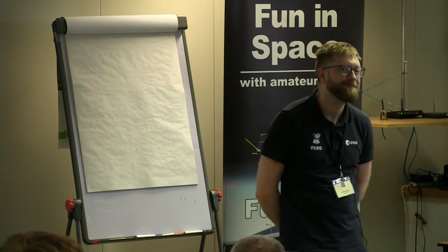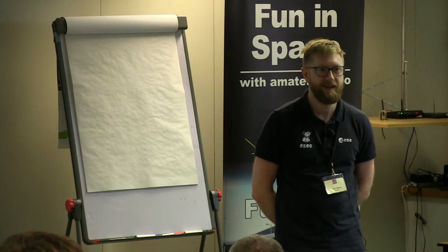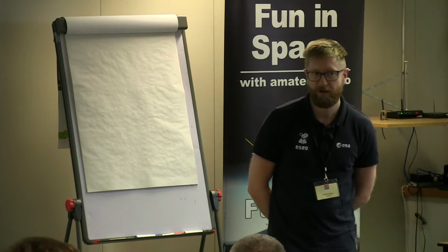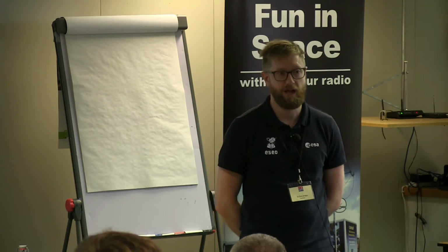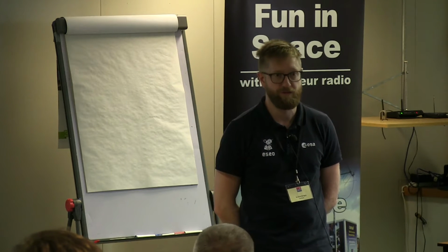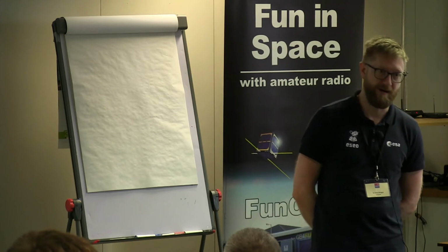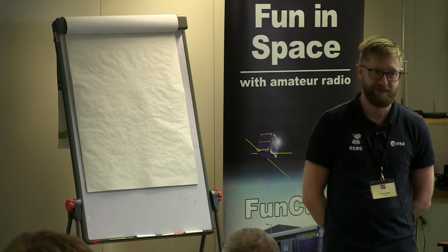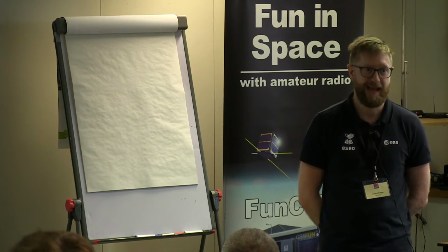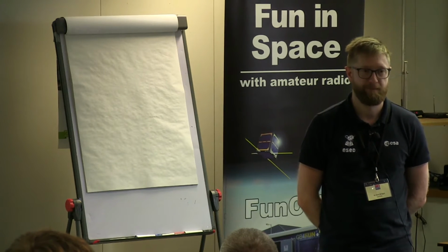A further question. SD cards. SD cards, yeah. And Raspberry Pi. Uh-huh. Not necessarily space compatible. No, I think they're okay. It depends what you're doing with them. So you can create Raspberry Pi images that are read-only. And so again, it comes back down to your mission need. Like, do you need to write things, or can they act as just routers and run everything in RAM? Yes. And especially if my RAM is TMR'd in software, my processor caches are Hamming error corrected, and my processor registers are duplicated. Yeah, I was partly thinking of the mechanics.